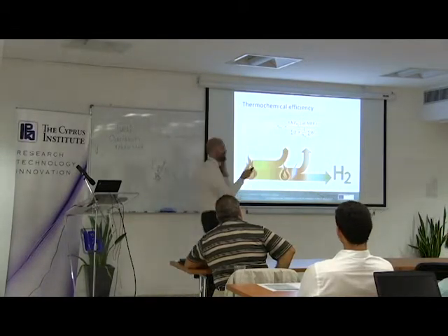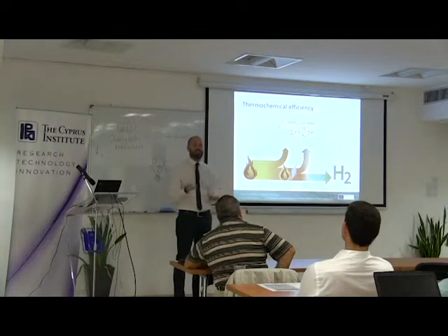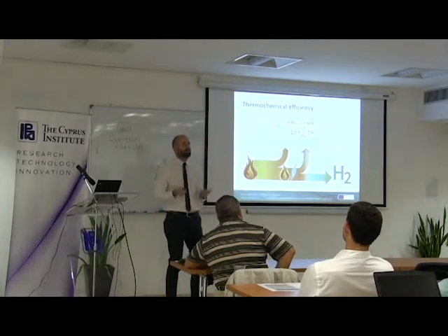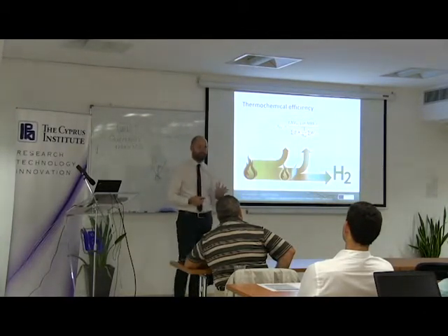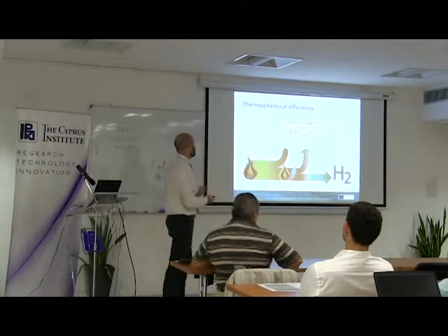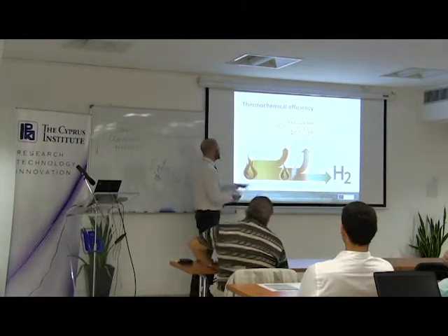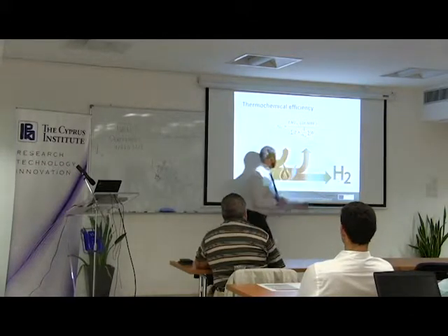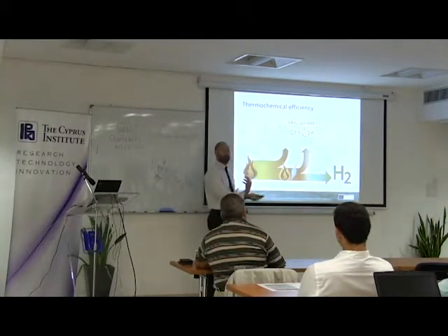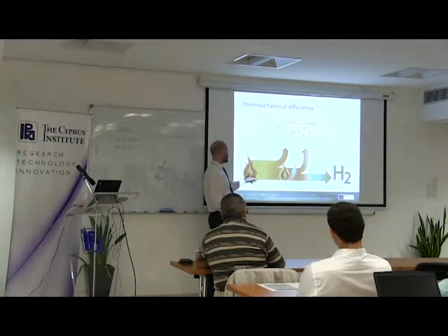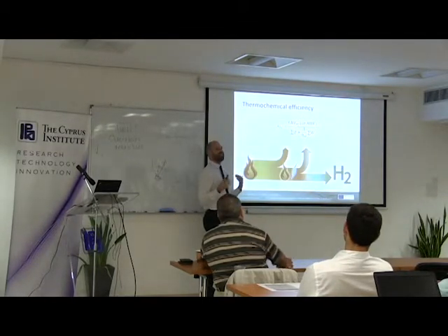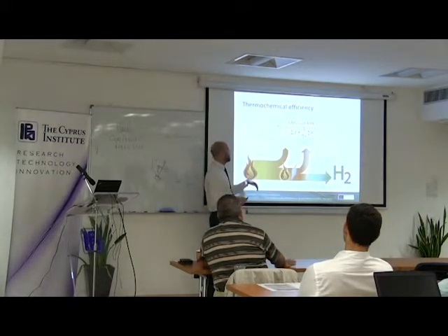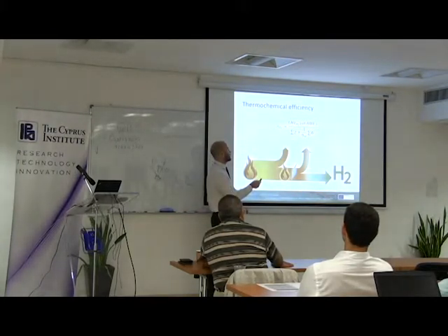So we need a metric that allows us to quantify this different value of electricity and heat. Either you use an exergetic approach in assessing the efficiency, or you use the so-called thermochemical conversion efficiency. We consider the equivalent heat entering the process, so this is the energy value of the hydrogen produced, okay? As the energy input, we take the heat as it is, okay?